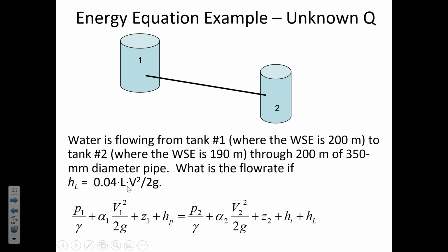Another is velocity, and it's velocity squared. So there's a really powerful effect. As the fluid moves progressively faster and faster, the head loss increases by velocity squared. And then, of course, we're dividing by 2g. So the tank on the left is the origin, location 1. Location 2 is the destination, where the flow is going towards.